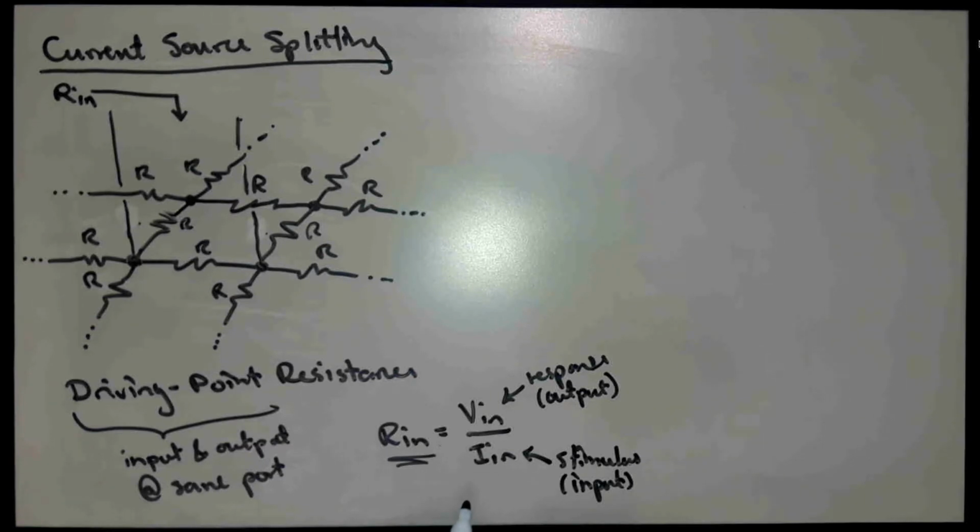So usually there's like a little, let's say, 100 microamp current source that's well calibrated inside your multimeter. And if you put it in ohms mode, it basically sources that 1/10 of a milliamp current out of its positive lead. And that creates some voltage drop across the leads, depending on what you hook it up to. And then it basically uses its voltage measurement capabilities to measure the voltage across the 2 wires, and then just divides the 2 things and prints out the display what the resulting resistance is.